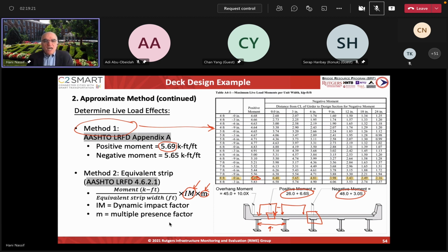So that's why, and this is Chan's thesis now, we think that the deck should have its own limit state, because the loads are underestimated. The axle loads in the WIM data, we're seeing them even twice as much and three times as much with the tandem and the tridem. And this is our legal. Tridem and tandem are legal.